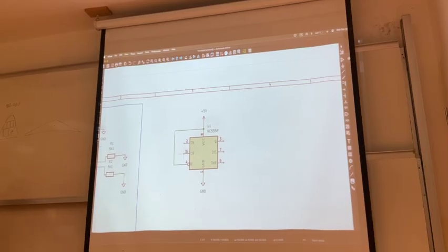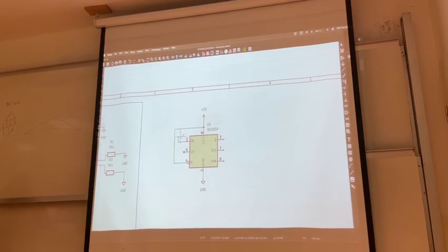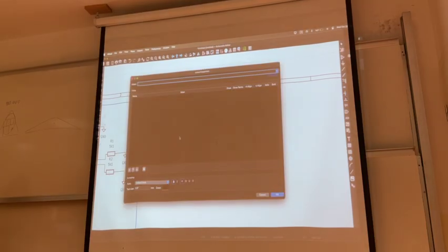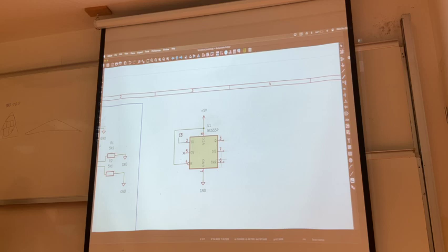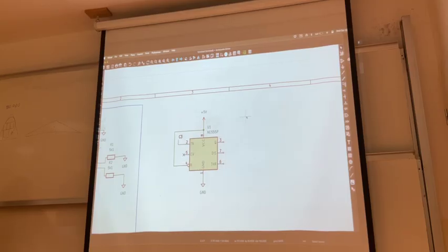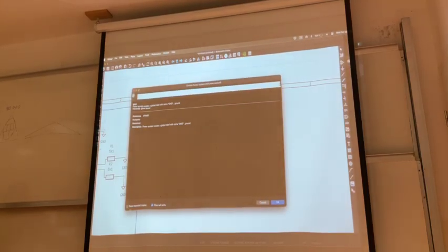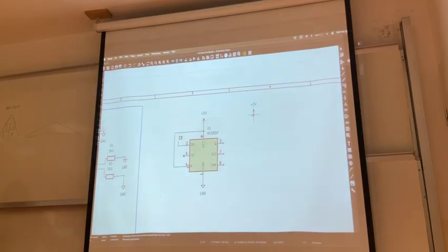I'm not going to connect here, so I'm going to press Q, not connecting. Okay? I'm going to make a wire here, like this, and I'm going to press double click to just finish the wire unconnected. I press label, I label it C3, bam, I'm going to connect it to somewhere else now. Later on, this is okay. I'm going to add another power. 5 volts. I add it here.